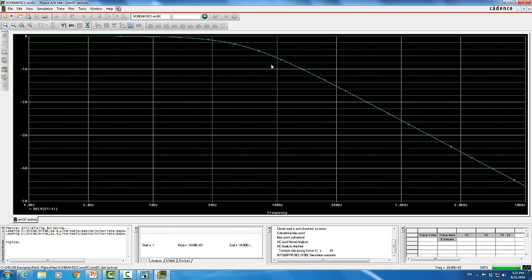So it's clear that the straight line here is going to be negative 20 dB per decade, because it's a first order filter, and when you hit the negative 3 dB is somewhere around here. So this is 2, 3 is somewhere around here, roughly around the 50 hertz. So around 50 hertz more or less, you're going to have the negative 3 dB corner frequency, right? So in any case, this is the frequency response of a first order filter, right? And that's what we have.